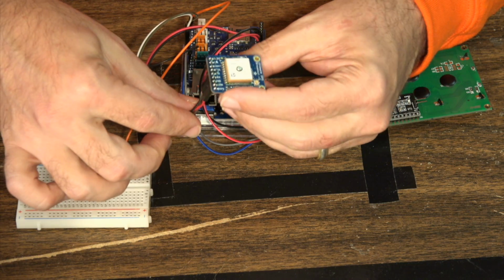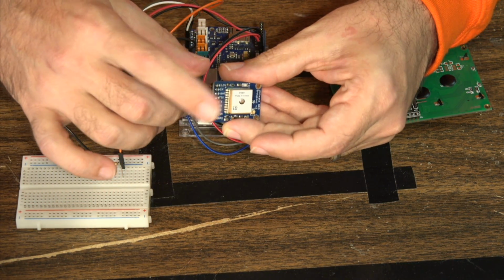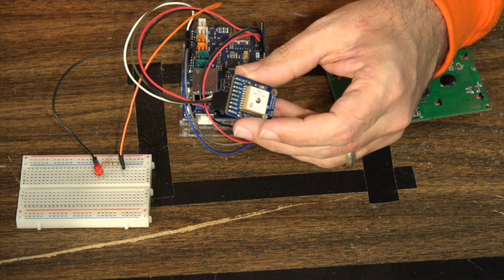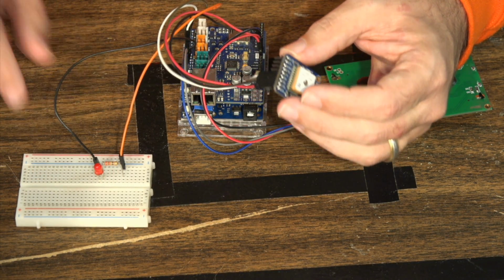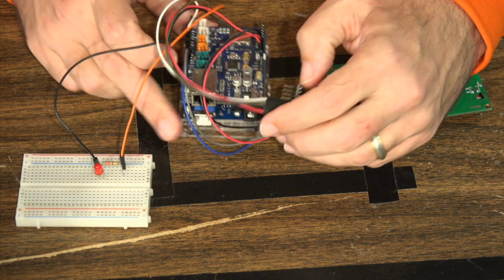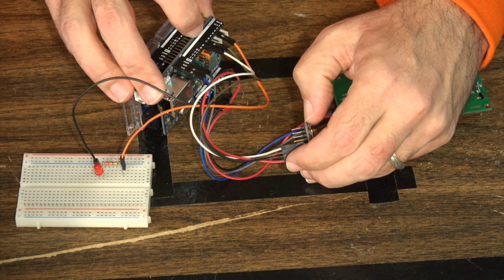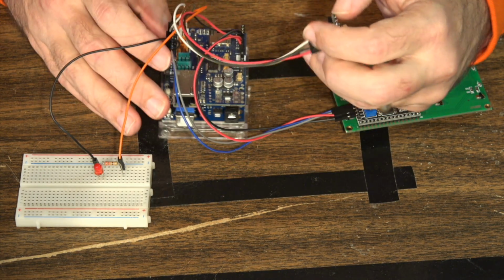Then we have our Adafruit. This is that Ultimate GPS. For this, again, this can be powered off of 3 volts. So we're going to be connecting this to the 3 volt connector for the power. I'm not going to split it through the breadboard here. We're going to be connecting it to ground. And then for the transmit and the receive, we are going to be connecting these to digital pins 7 and 8 on that Ethernet shield.